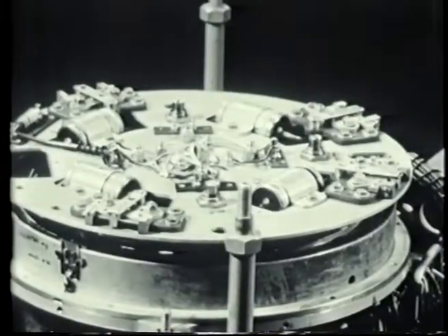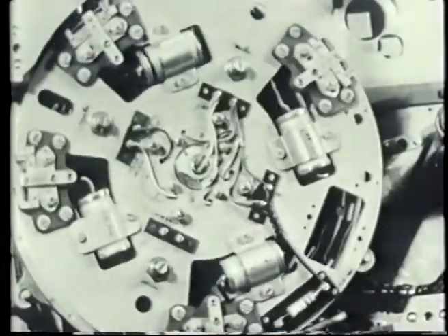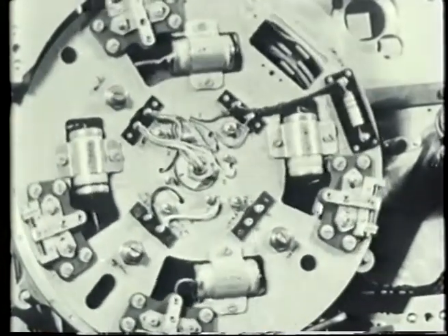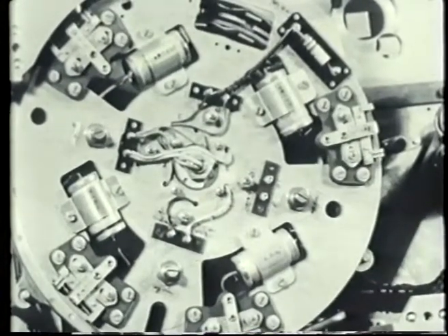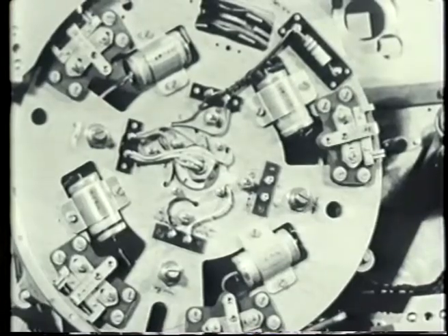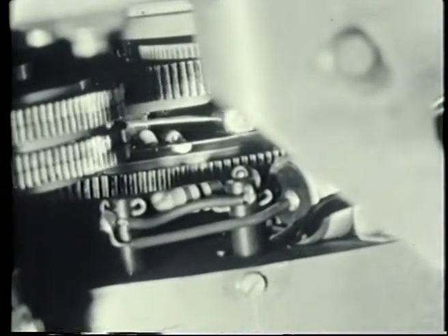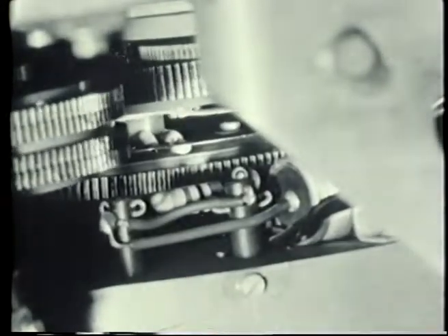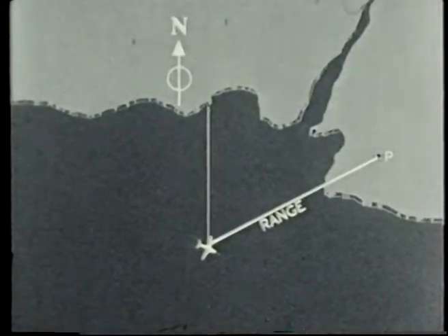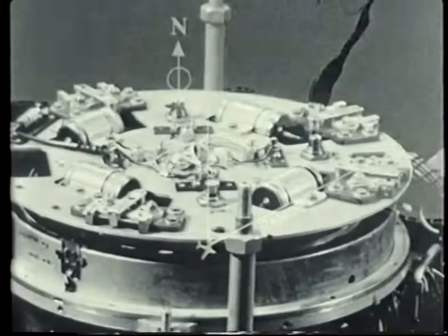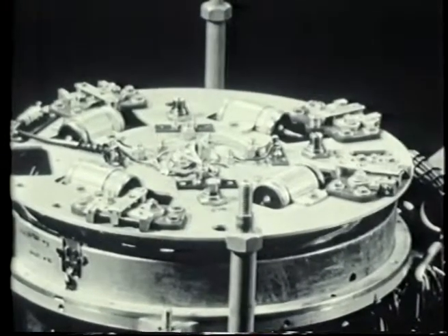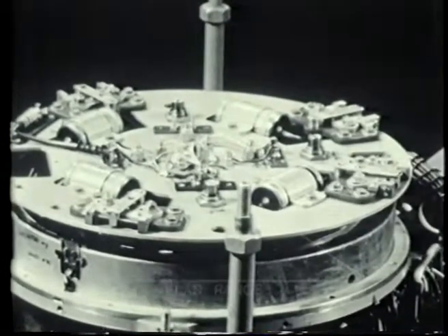As before, the angular position of the shaft of the sine-cosine potentiometer gives the bearing of the point P. The potentiometer shaft moves a pair of contacts. These are closed by a roller driven by the mag-slip shaft. When they close, the PPI trace is momentarily brightened and gives the bearing of the point P relative to north. The compounder also delivers the plan range of the point P as a voltage.